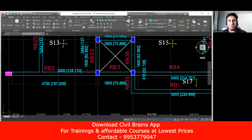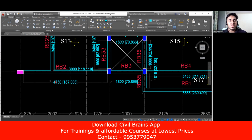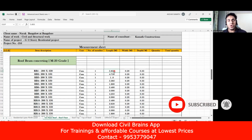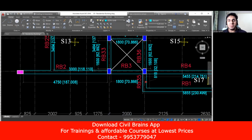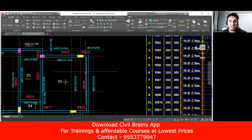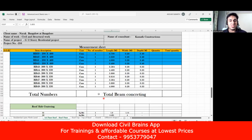Let me verify that RB1. Yes, it is 5.855. Next, what is RB2? RB2 is 4750. This complete beam is RB2, from this column inner to this column inner, 4750. So come here, you see 4750, 4.75. In this way, all the values up to RB49. We have 49 beams. RB49 is the last one here. RB49 is 4900, and you can see here I've entered 4900. You're getting my point. Done.